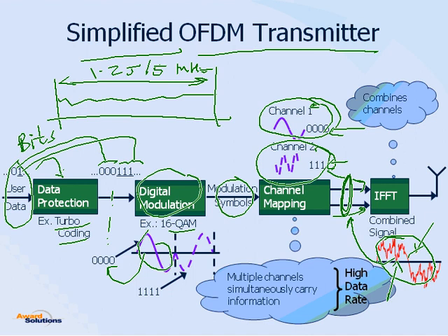Okay, it just looks like noise. Same way here, this signal looks like noise, but just like a CDMA signal has orthogonal Walsh codes and OVSF codes carrying the data, same idea here. Even though we have these noisy signals, it looks like a messed up signal. Inside that messed up signal, we have orthogonal subcarriers, each subcarrier carrying a modulation symbol. And this is all baseband. Okay, then we add cyclic prefix, do the frequency up conversion.